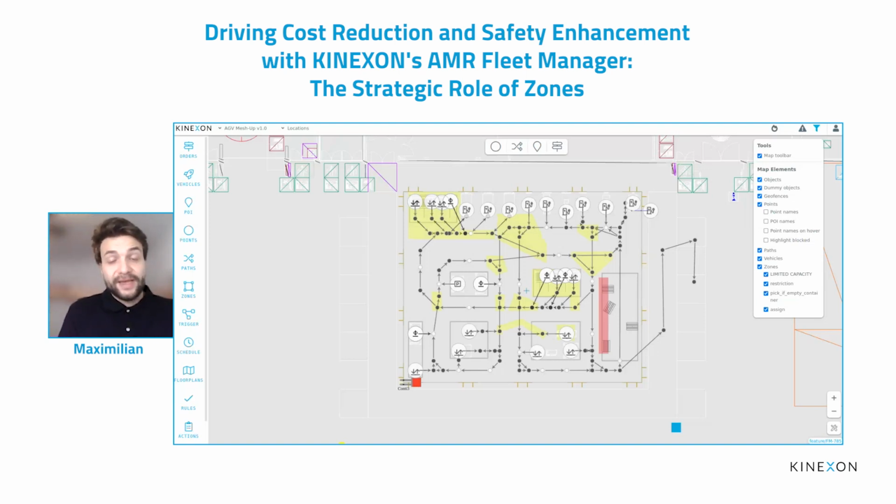Also, based on that information, we have another advantage: if you don't have to transform the whole logic of the old robots into the new system, the integration effort is much lower, and you can rely on your operations continuing to drive as they drove before. Of course, it is in most cases preferable to also fully integrate the robots, which we also do on VDA 5050, or a proprietary interface.